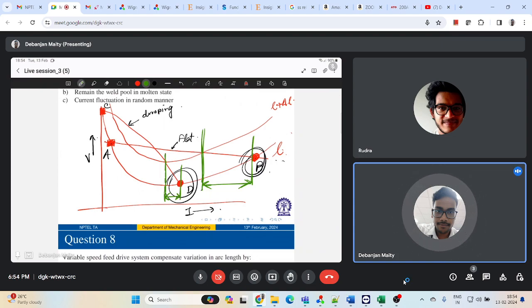Now in manual arc welding, you will have some inadvertent change in the arc length, which is inevitable. There will always be change in your arc length because you cannot control the melting electrode perfectly, since you are doing it manually, right? However, that should not cause a large change in the welding current. Because you don't want a large change in the welding current, that sharply drooping characteristic is desirable for manual arc welding.